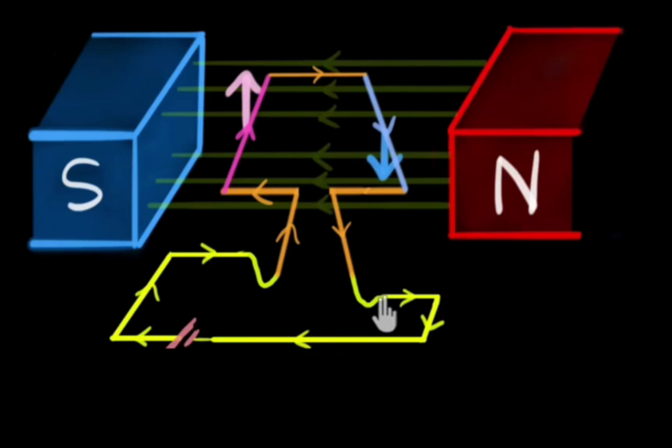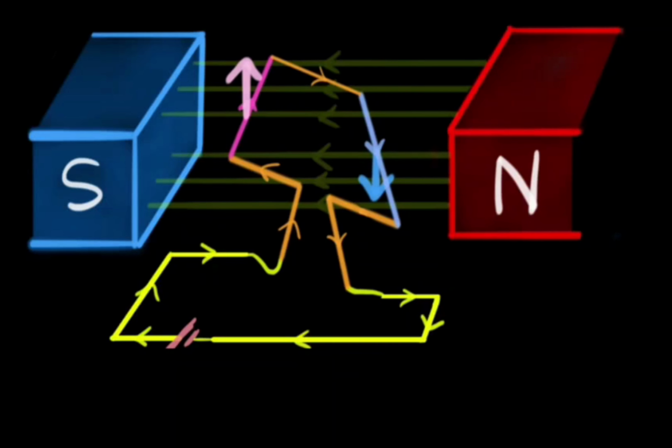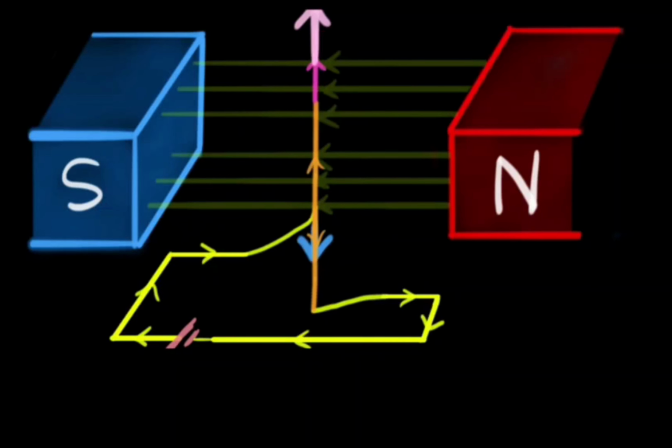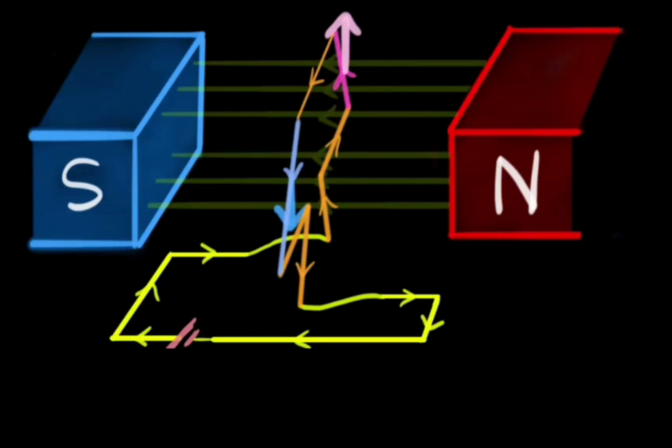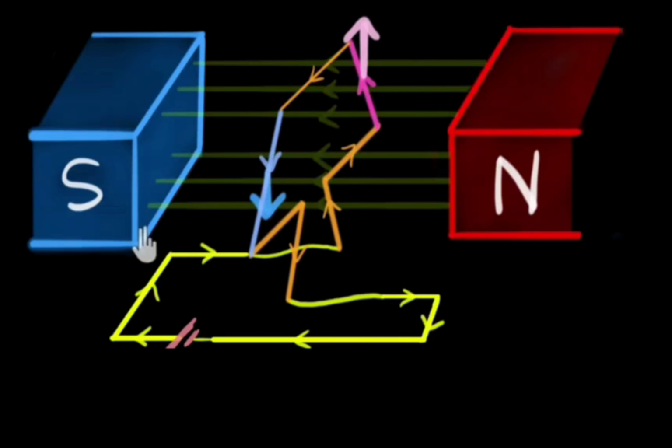That this is so can be deduced from Lenz's law, which states that the direction of an induced EMF is such as to oppose the cause producing it, which is of course the applied voltage. The magnitude of the back EMF or counter EMF can be calculated using the formula for the induced EMF in the generator.